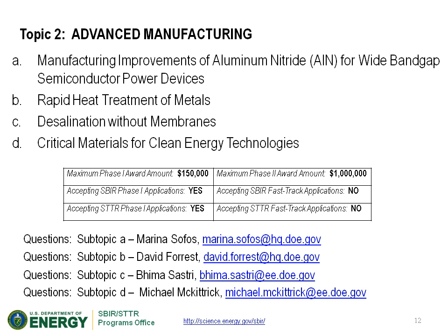Another opportunity exists in terms of novel heat treatments of various materials that could result in a much finer grain size that maybe would enable superplastic forming, or would allow you to take advantage of the kinetics of diffusion and phase transformations.